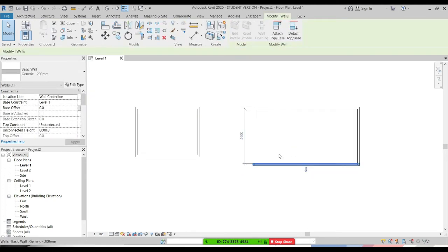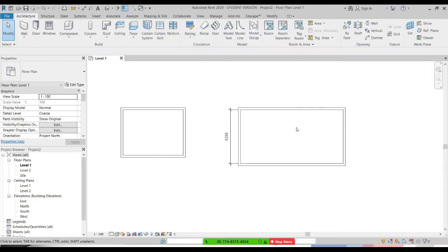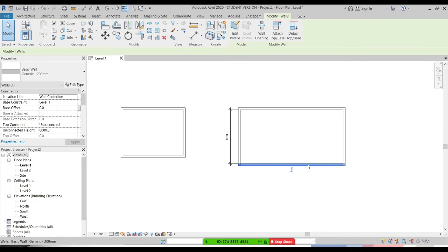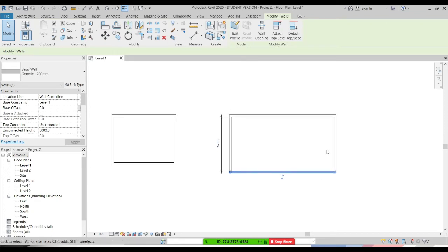To move any of your elements, you need to first select it. So let's see how we can actually select elements. If I need to select a single element, you simply click it with the left click mouse button. If I need to select more, then I'm going to press the control button, and you can see that my cursor now has transformed. It has a plus icon near to it. I can click on more elements to select them. So this is one way of selection.